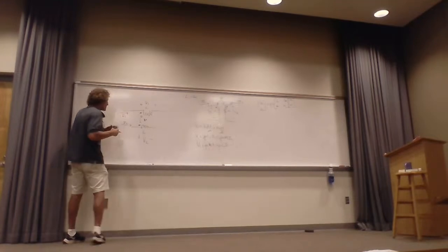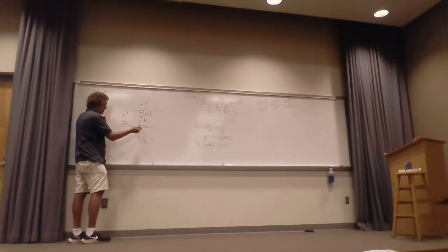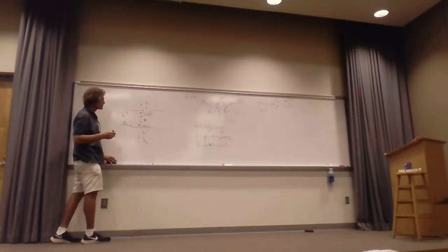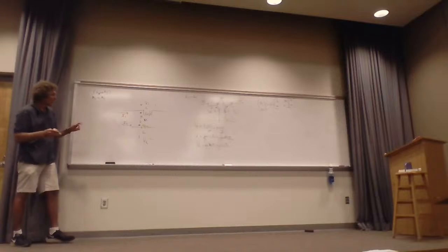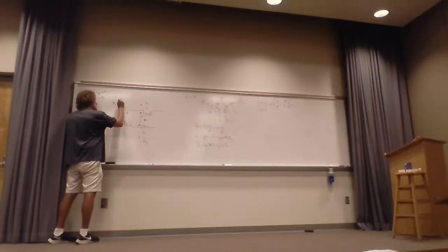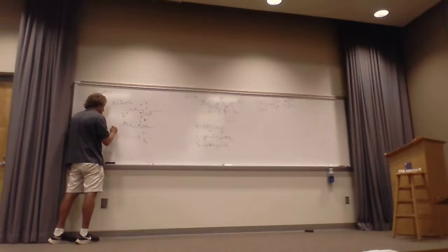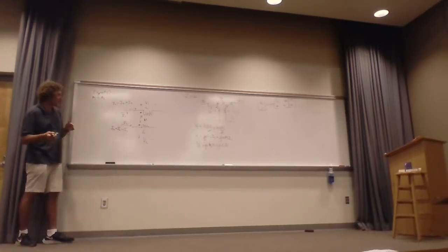So when I take a look at this, those are the equations that govern it. They govern this too. I just put them that way because you're used to seeing it that way, right? Here's V1, there's V2 as I've drawn. So I say that I1 can be composed of both a common mode current and a differential. Now the differential is flowing that way. And I can say I2 is composed of a common mode current minus a differential, because the differential is going to be in the opposite directions.